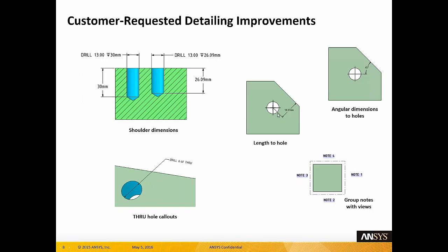You can also do dimensions to the center of holes that appear on a face. Before, and based on true ASME standard, you're supposed to define a reference frame here first. We found that customers just didn't like the need to take that extra step, and so now we allow you to create a dimension directly to the center.